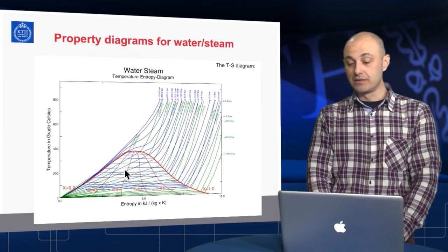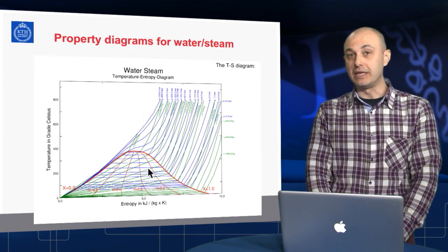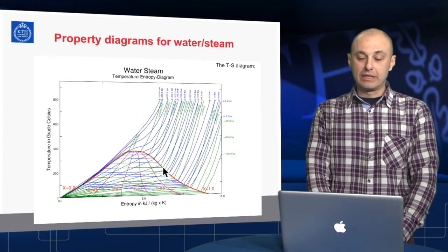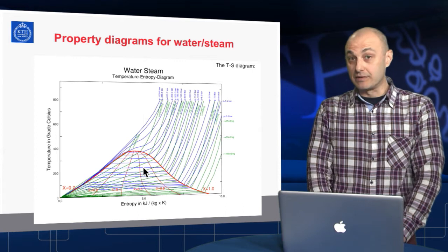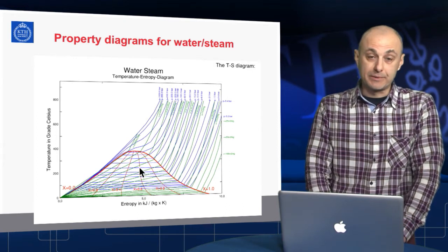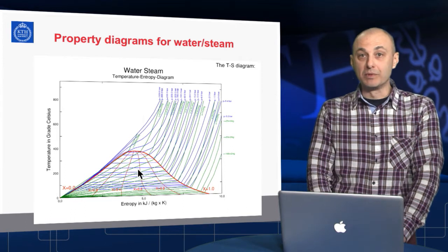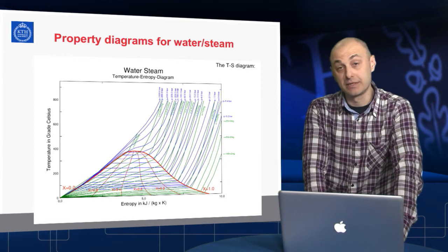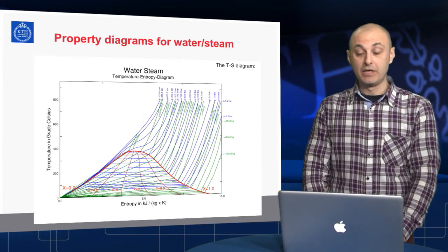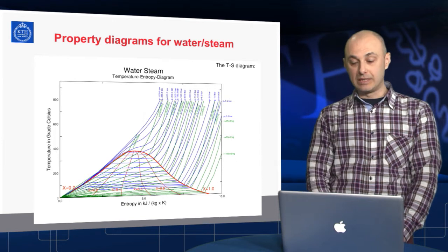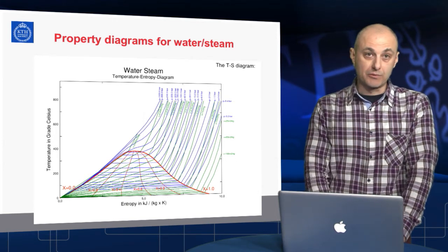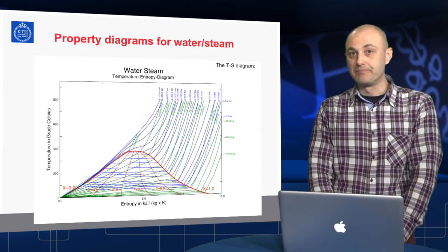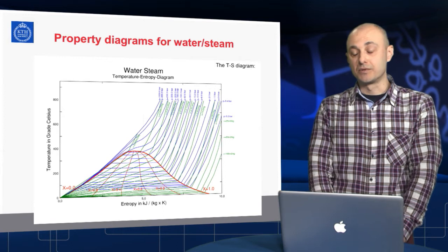Entropy allows us to represent an exchange of heat, that is energy being moved from one object to another object, in the case of most often heat being transferred at constant temperature. We do not, as humans, in the way we comprehend nature, understand really how heat and energy can be transferred at constant temperature. But entropy helps us, in practice, to put this into an equation. Energy being transferred when temperature stays the same. Typical example, boiling and condensation.